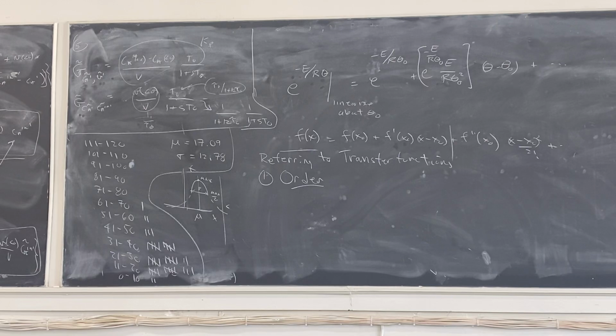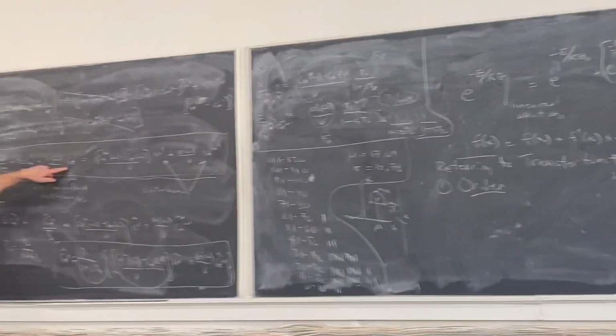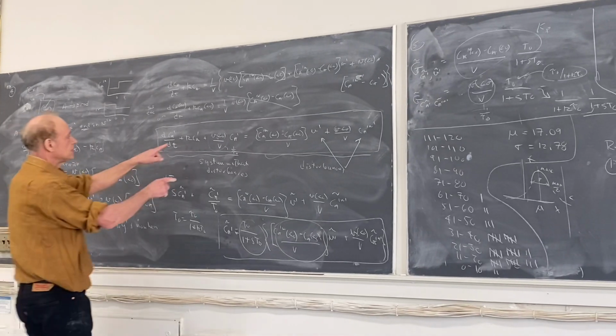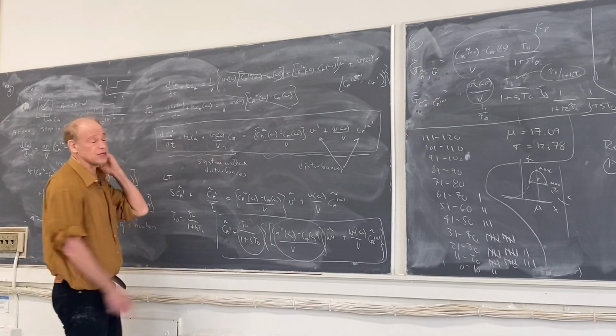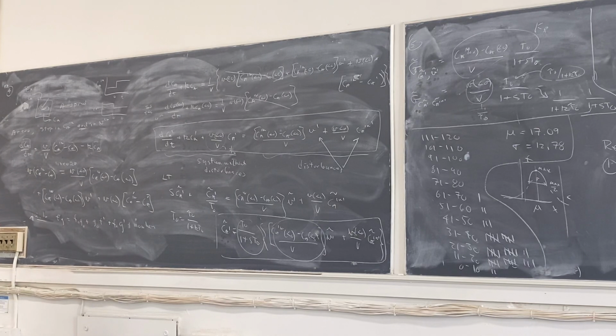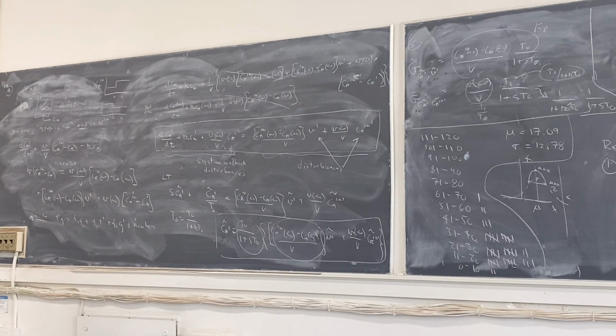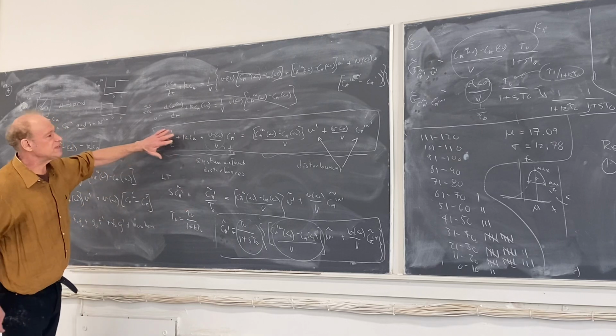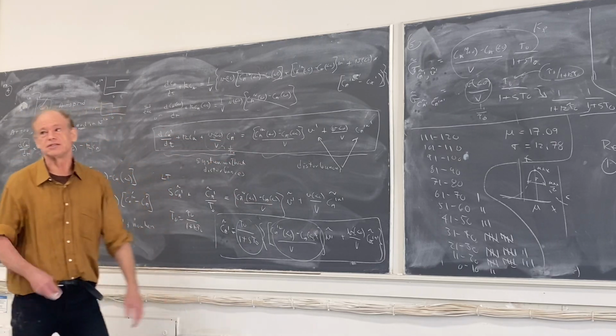Remember, this is the Ca prime dt plus a constant times Ca prime. That's all, and the constant, k plus 1 over tau 0, is the time constant of the system. It has nothing to do with the disturbances. It's the natural part of the system. The disturbances are on the right. So the left is the system, the right is the disturbances.